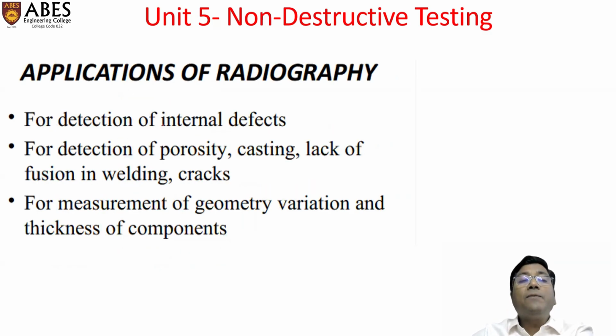Applications of radiography: it is applied for detection of internal defects, for detection of porosity in castings, lack of fusion in welding, and cracks, and for measurement of geometry variation and thickness of components.